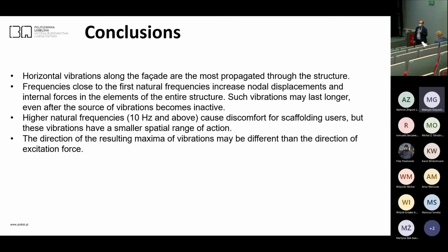Sometimes the direction of excitation was completely different from the ones that we observed as excited ones. When we tried to move along the facade horizontally in the facade of the scaffolding, sometimes we observed vibrations perpendicular to the facade of the scaffolding. It was just common.